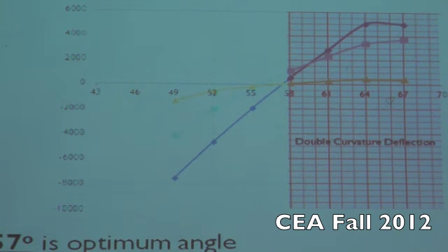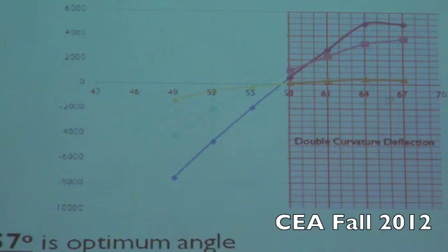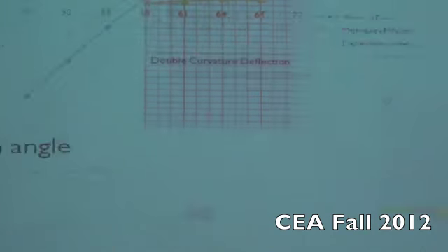So finally, we reached the conclusion that the optimum angle of inclination for the pylon is 57 degrees. It's only 1 degree different from the actual pylon. This is because we chose the one with the minimum deflection, and although it has a moment higher than the other value, like the 55 degrees, this moment will be decreased due to the application of different variables.